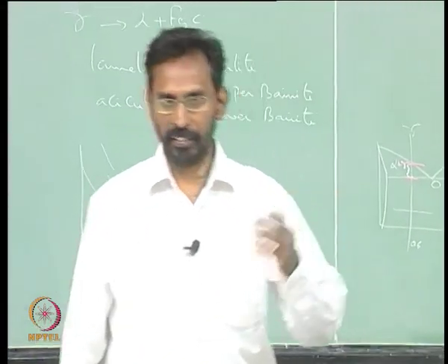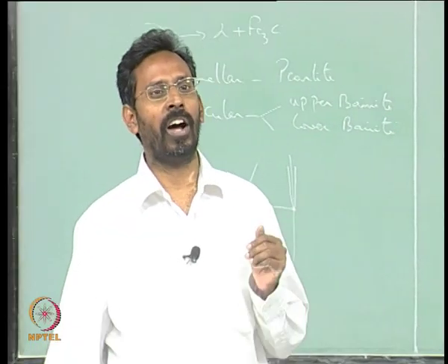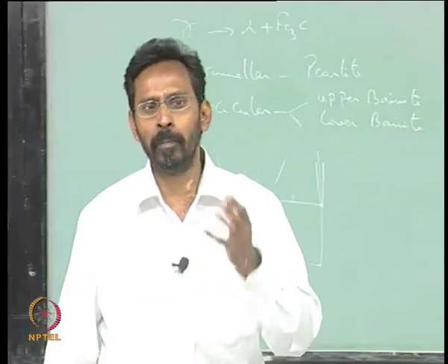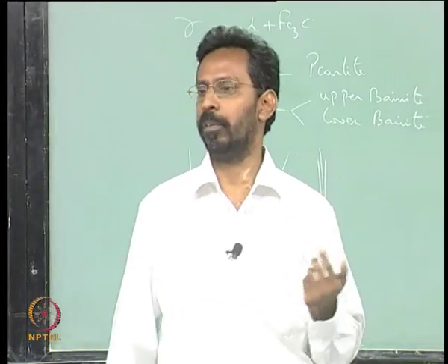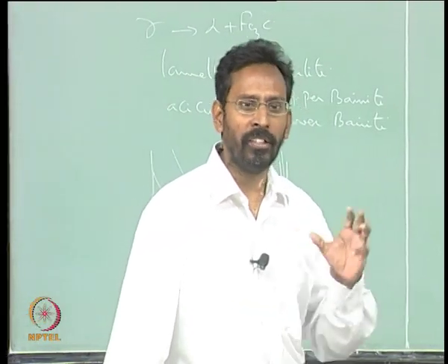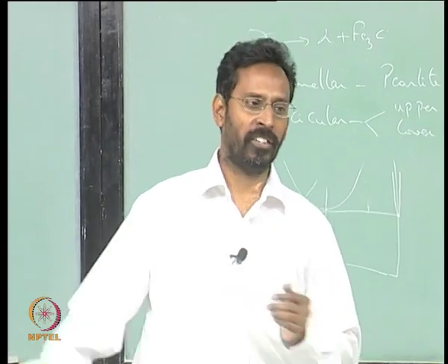Martensite forms by a shear transformation of one structure to the other. That is why the FCC structure of the austenite shears and gives you martensite, whereas pearlite is already a two phase mixture with two different structures and two different compositions. Such a two phase mixture cannot shear and give you one single phase structure.